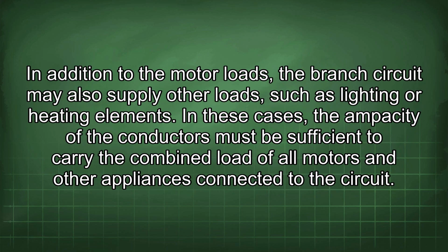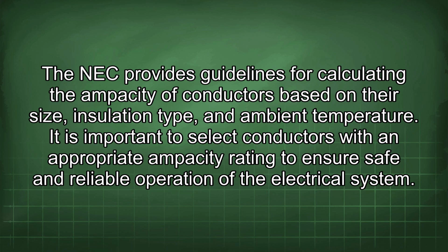In addition to the motor loads, the branch circuit may also supply other loads, such as lighting or heating elements. In these cases, the ampacity of the conductors must be sufficient to carry the combined load of all motors and other appliances connected to the circuit. The NEC provides guidelines for calculating the ampacity of conductors based on their size, insulation type, and ambient temperature. It is important to select conductors with an appropriate ampacity rating to ensure safe and reliable operation of the electrical system.